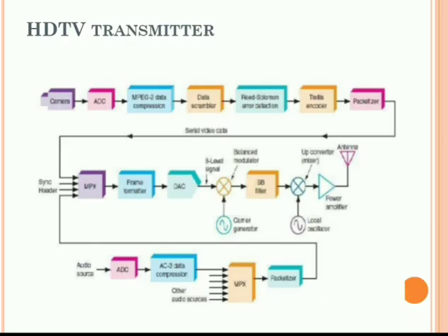After that, the serial data is sent to a D to A converter, where each sequential 3-bit group is converted to a discrete voltage level. This particular system encodes 3 bits per symbol, thereby greatly increasing the data rate within the channel. For example, each 3-bit group is converted to a relative level.